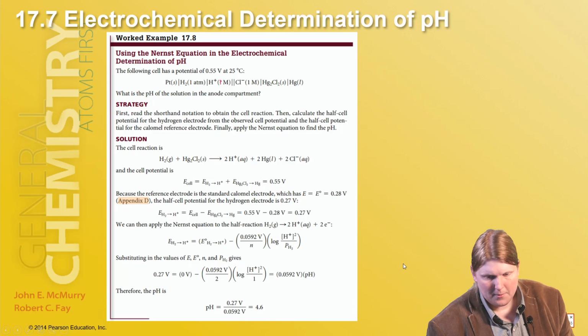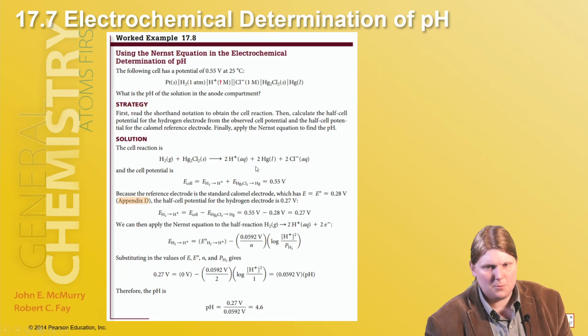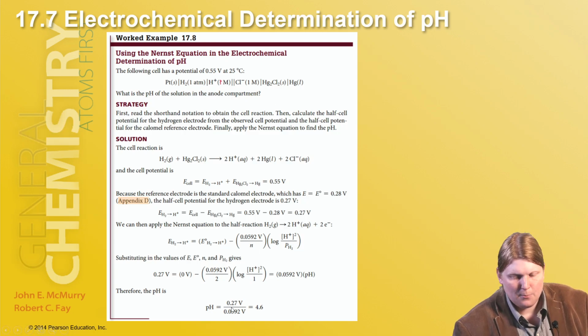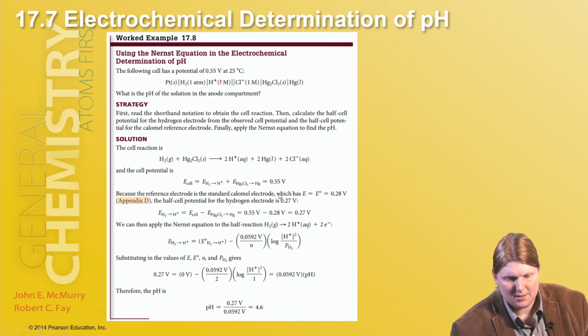Cool and interesting. But this is the basic principle by which the pH electrodes work. You can use different reactions. It doesn't always have to be this one. But the basic principle is being able to measure a gradient across the membrane, this glass electrode.